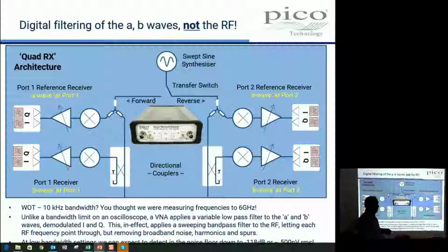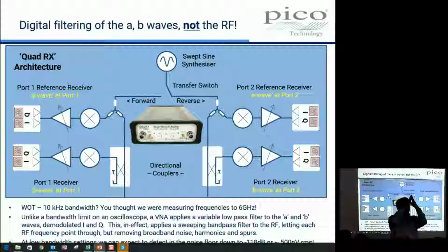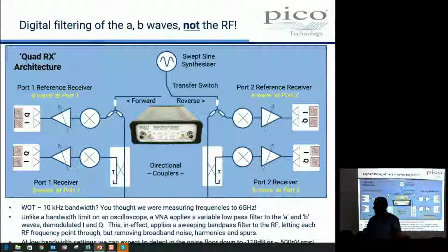But yes, a VNA or a frequency domain product, a spectrum analyzer, is the same. You can have a 1 hertz filter on a spectrum analyzer, and it just makes the frequency much sharper. We must have the same content on the FFTs, I suppose, as the resolution of an FFT changes. The FFT should increase the sample, which is effectively what the filter's doing, isn't it?